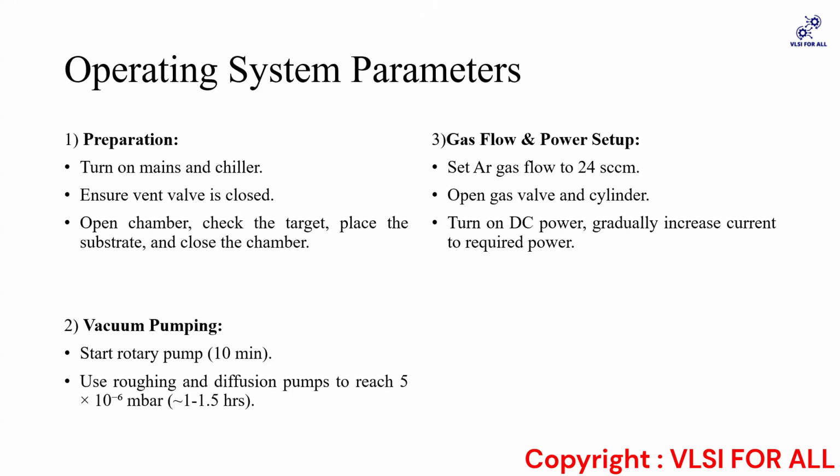And the operating parameters which have been used for this deposition: for the sputtering technique, there is RF sputtering and DC sputtering. For that, we need to make sure of certain parameters such as gas flow, temperature, time, film thickness, uniformity, deposition rate, and density. Eventually, temperature also plays an important role.